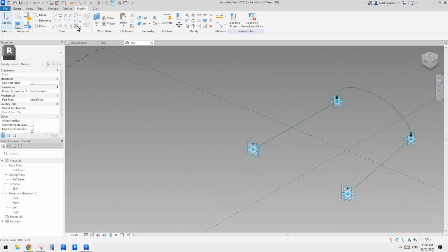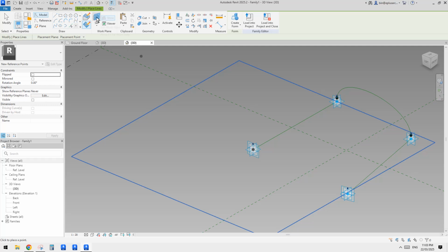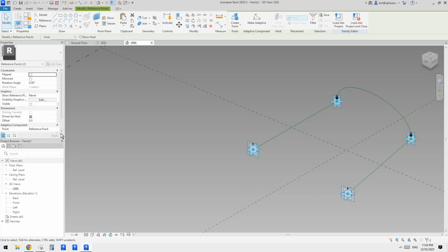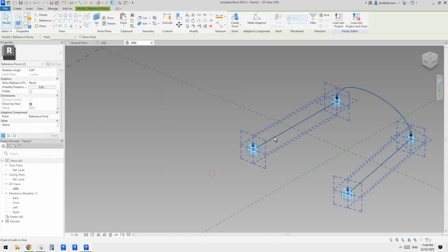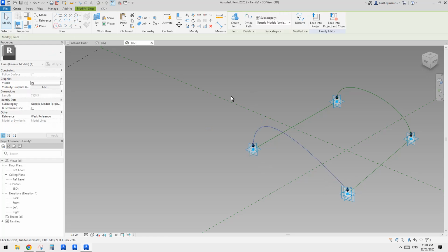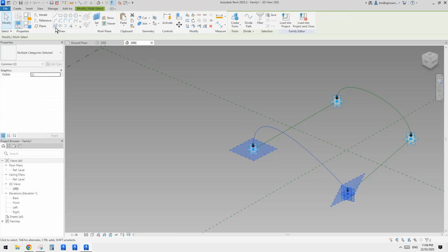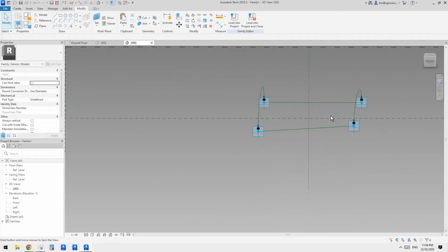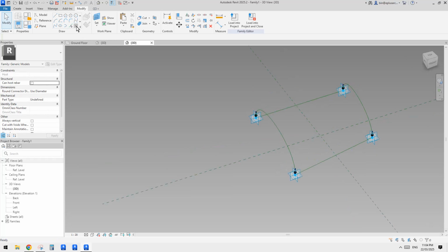So do the same. Another point here. Another point here. Select the point. We're going to use the same offset, so let's link that to Offset 1. And select the 1, 2, and 3 points. Spline through points, reference line. Select, Control select, spline through points. Okay, so now we have this. So we have 1, 2, and we need another one. So the third one,